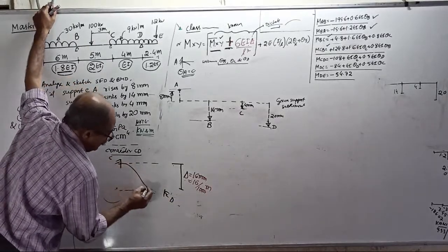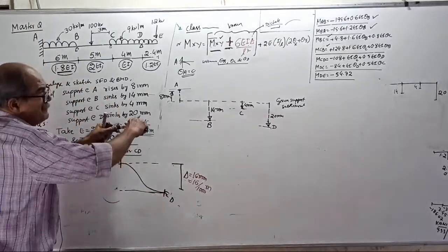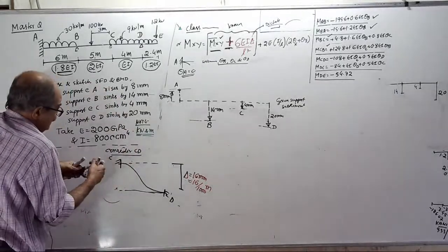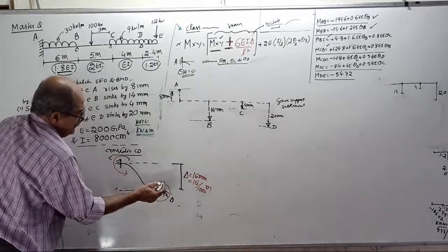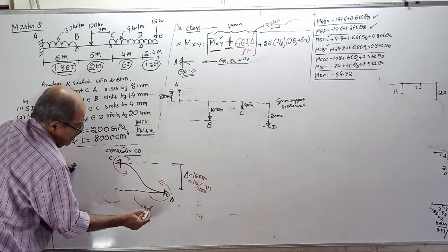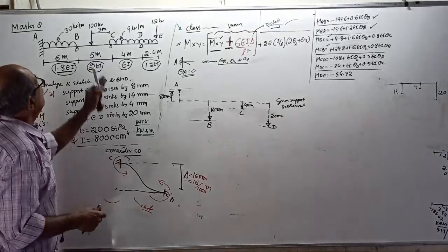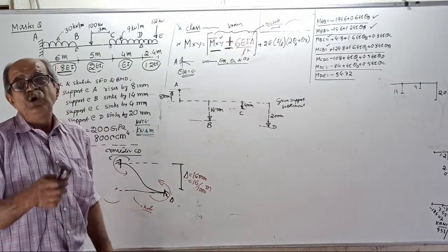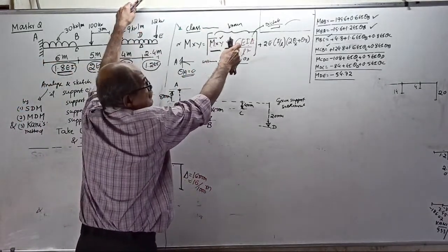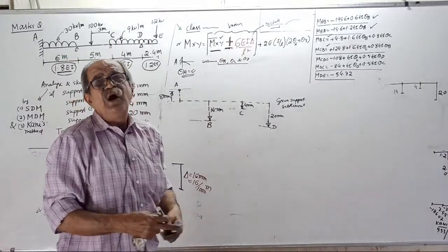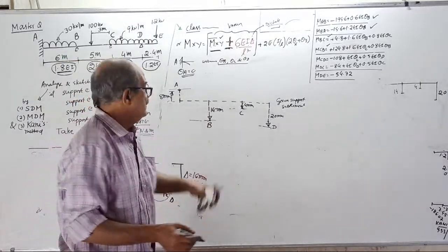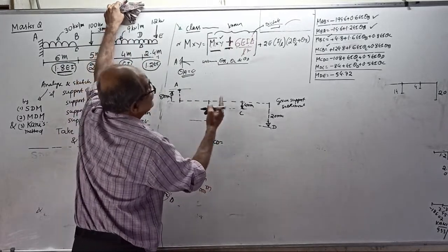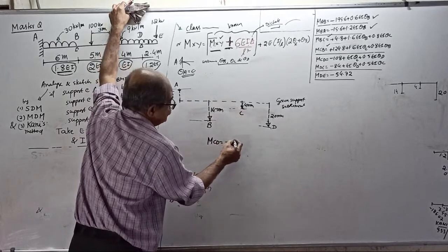The elastic curve will come this way. Therefore, if the member sinks this way, the reacting moments are anti-clockwise. Both are anti-clockwise. Make a note: FPMs for CD due to delta, both are anti-clockwise. Therefore, use minus sign for this term. See, in the master example, all terms came, some plus, some minus. So, on that basis, M_CD equals M bar CD, M bar CD is minus 12.